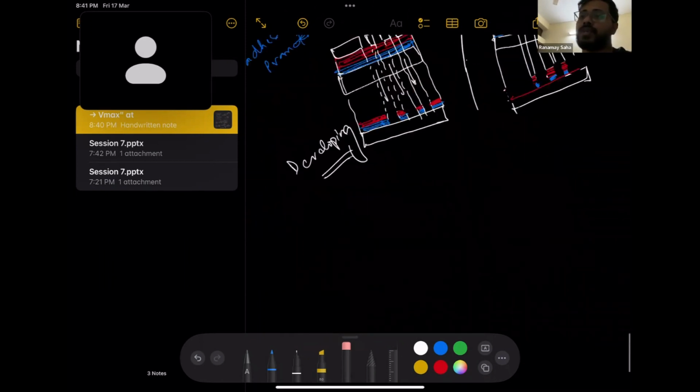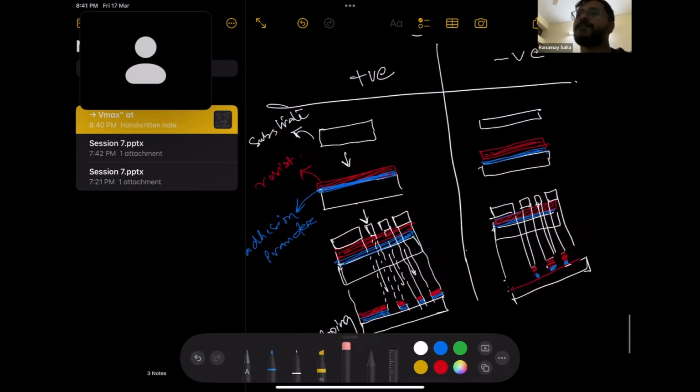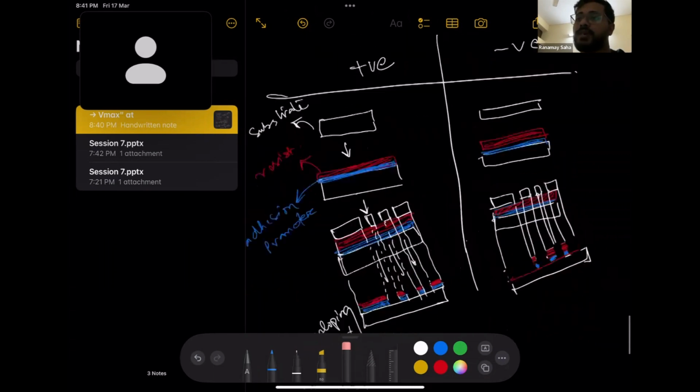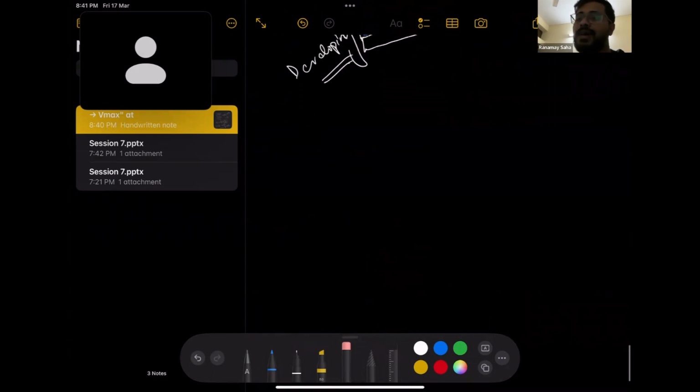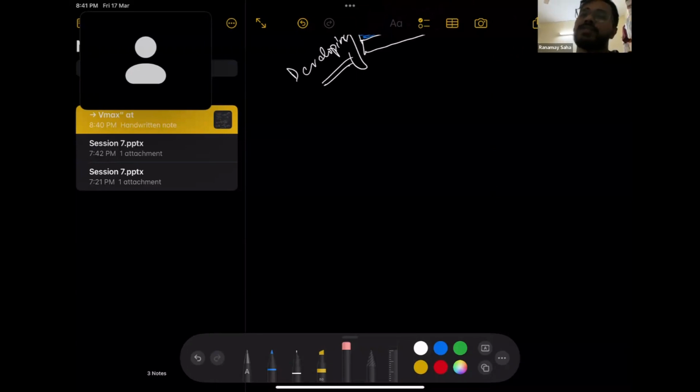Next, I hope it's clear, right? This leads to the last topic of today's session, which shows you the steps of the photolithography process in detail. Majorly we have a patterning step, exposure step, and a developing step, right? But in detail, firstly you have to do the substrate cleaning.